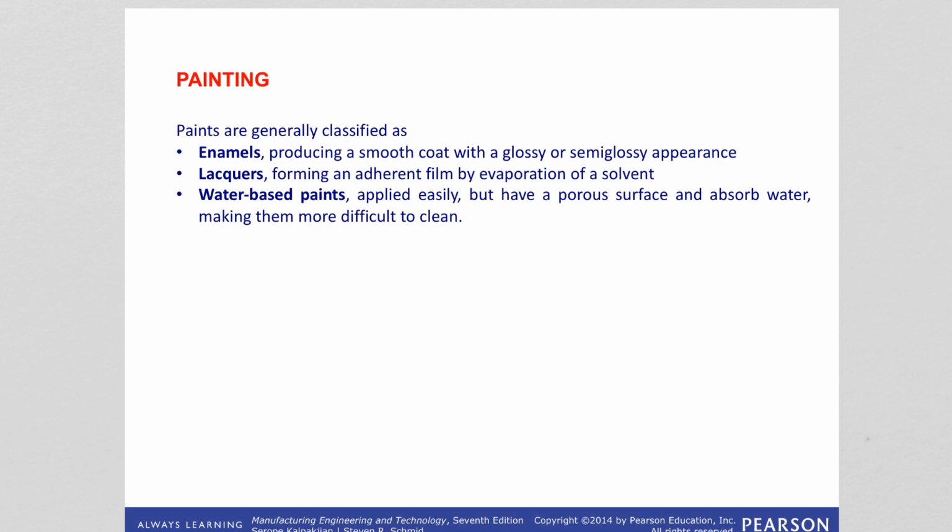So in this case, enamels are producing a smooth coat with a glossy or semi-glossy appearance. Lacquers form an adherent film by evaporation of a solvent, and water-based paints are applied easily but can have a porous surface and absorb water, making them difficult to clean.